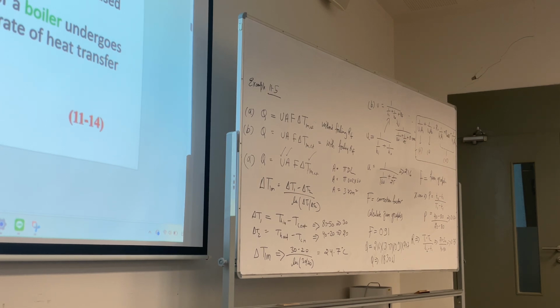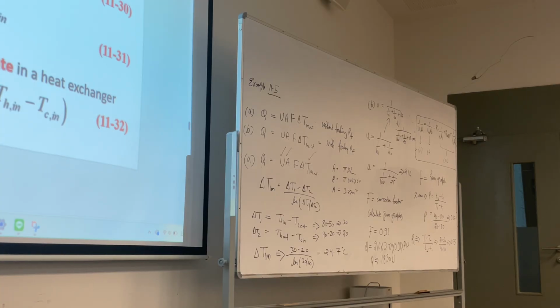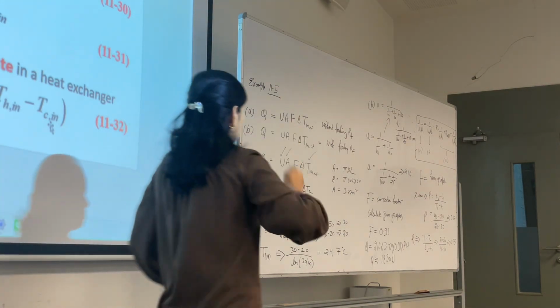Okay. So Q is this, and when you are calculating Q max, so this delta T max is different. Delta T max is the maximum difference in the temperature, which is going to be when there is a hot in and cold in. Epsilon is effectiveness, NTU. Heat transfer effectiveness. So epsilon is heat transfer effectiveness. I remove this.